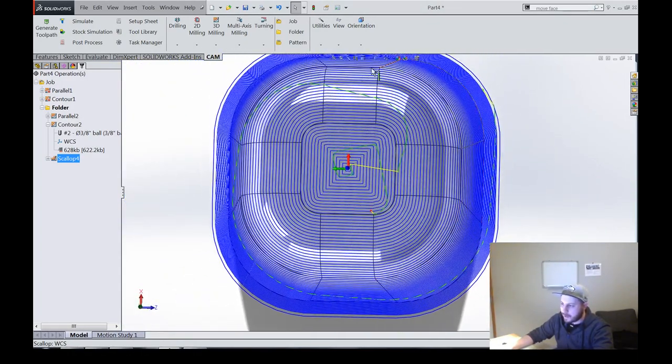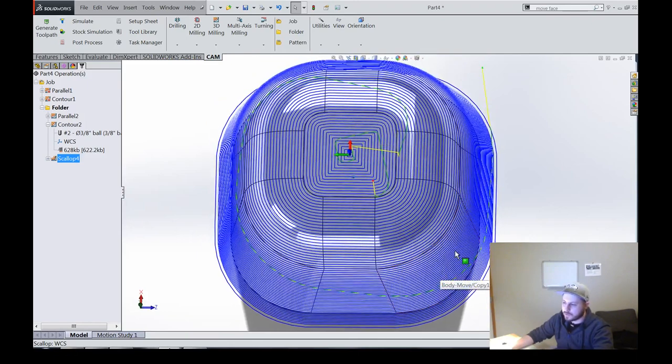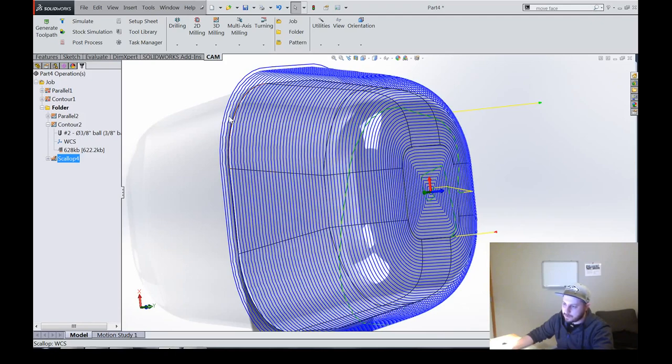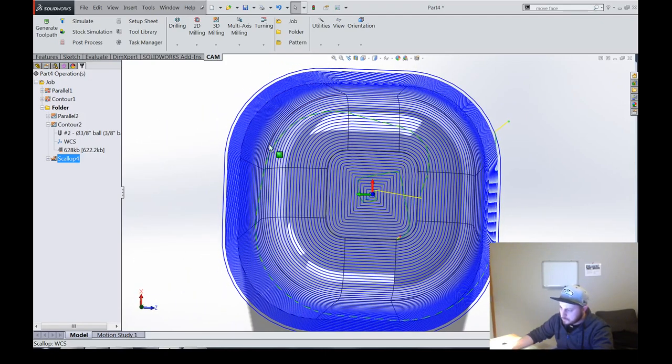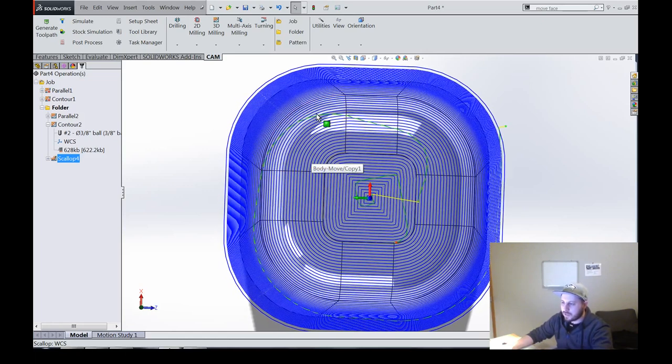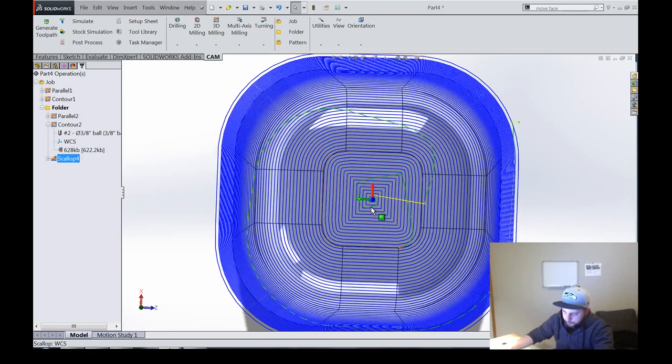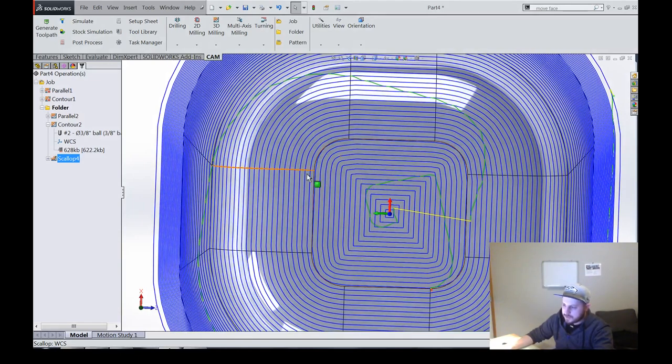It's offsetting the boundary curve, and that's super important for using Scallop. Basically what it's doing is it's analyzing what the slope is at a given point, figuring out how much it needs to offset that boundary by in order to maintain that constant step over along the surface, and it just continually does that. But at some point, what happens when you offset geometry, and you probably know this, is that eventually the geometry collapses and you get to where you have a radius and then that radius goes away. And with Scallop, that creates a problem.